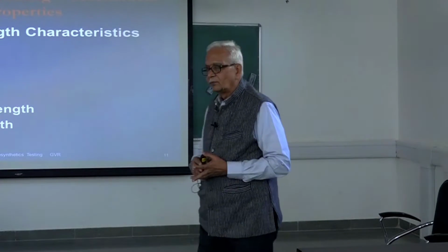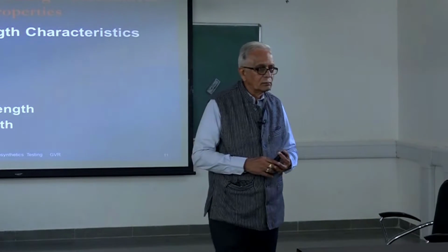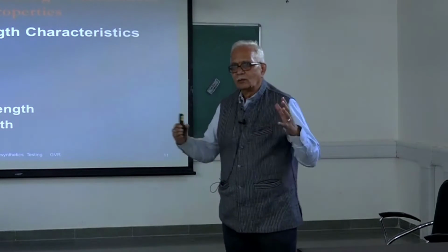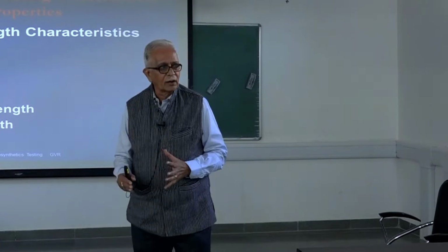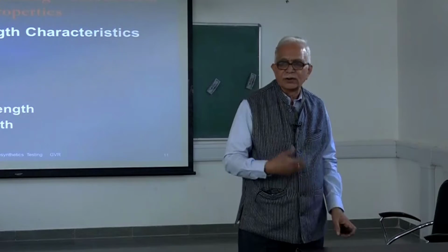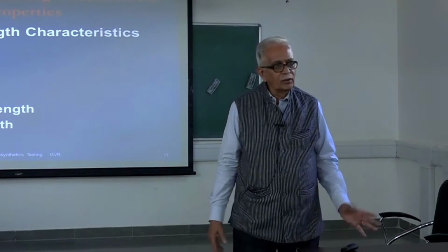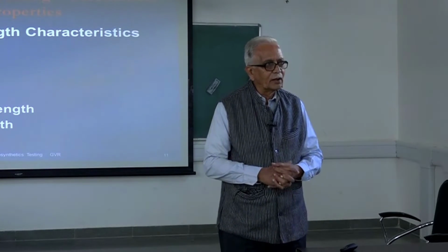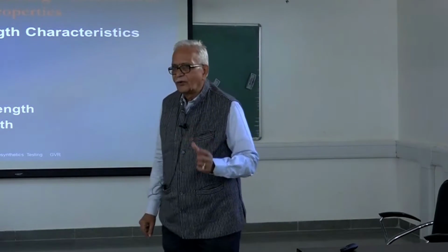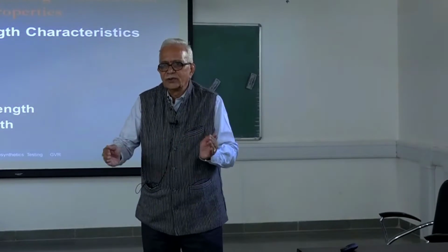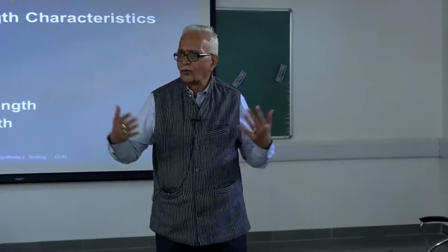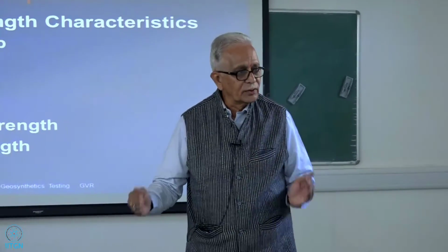Statistically, you do know? You take a case of a rock, let us say, about which you are familiar with. Why should you take a larger dimension piece of rock, intact rock, or should you take a smaller piece? Which one is likely to have more strength? If you take a smaller piece of material, it is less likely to have defects actually. If you take larger pieces, it is going to have the micro fractures, mini fractures, and even much larger ones will have folds and faults. Everything is going to be there in the larger the dimension of the specimen.